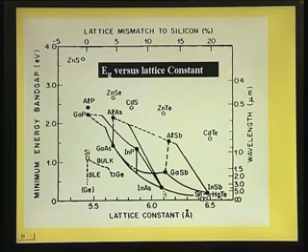You can mix them together, you can get a material whose band gap is anywhere from 1.43 right down to 0.36. Whichever band gap you are interested in depends upon your particular application. For example, I can just adjust the concentration of indium. This is gallium arsenide. I keep on adding indium to gallium arsenide, replacing gallium with indium, increasing the mole fraction of indium, then at a particular point it reaches here. Now, you can see a solid line is made here, that is, you can use that compound.